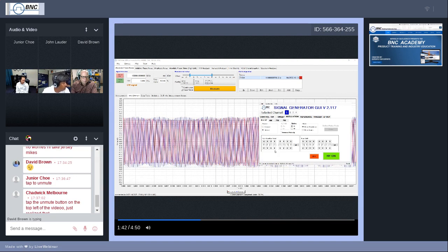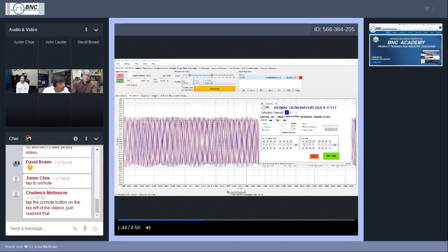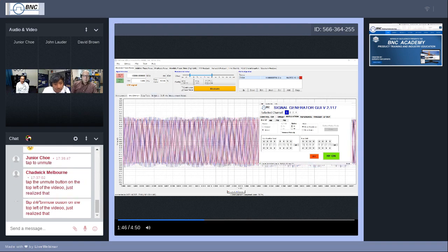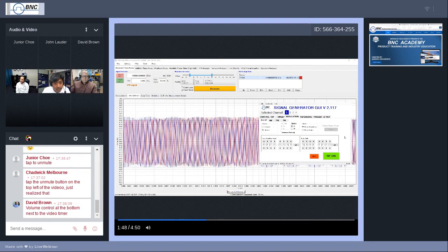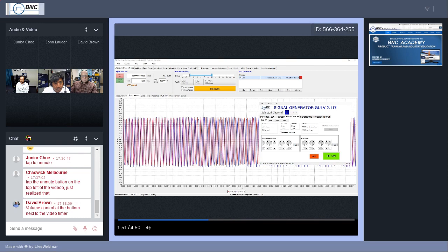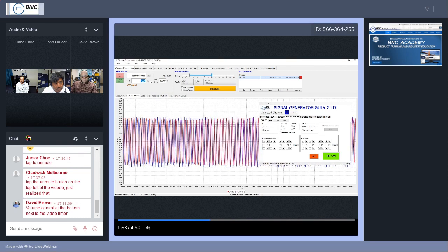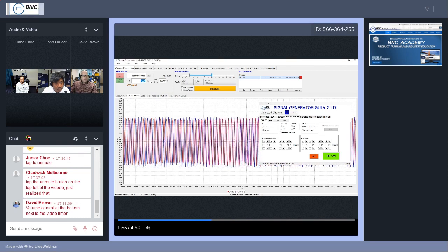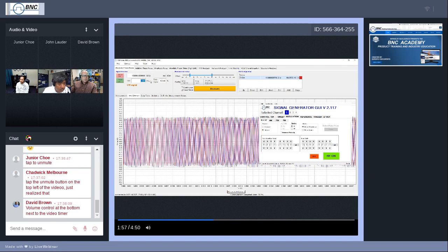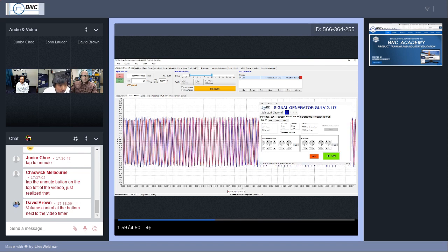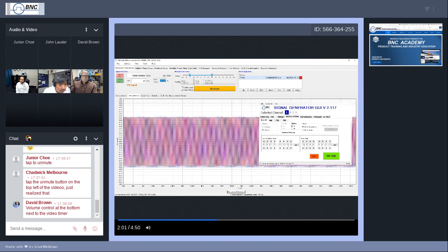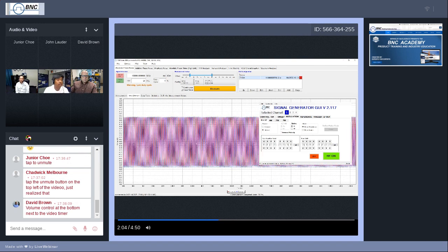I can let the device, or the PNT, automatically detect this information, or I can just enter it for faster processing. For 50 microseconds, that's about 20 kilohertz, and that's about 1% duty cycle.